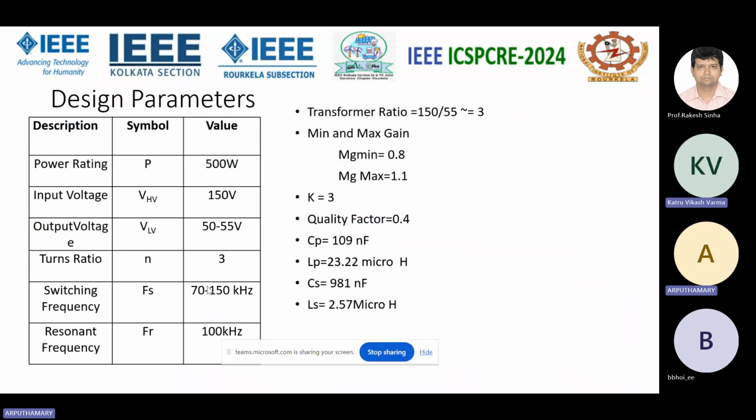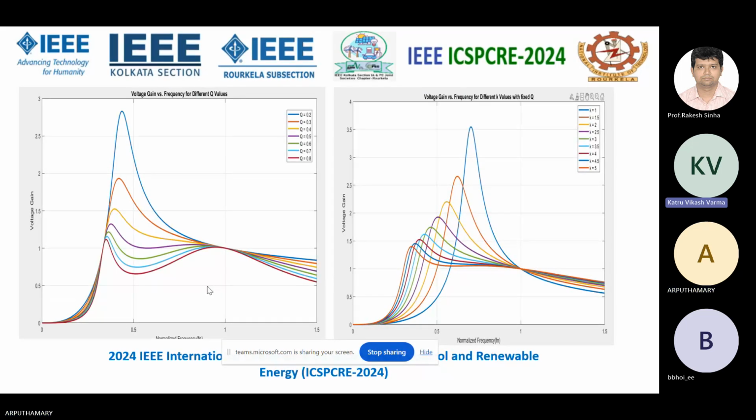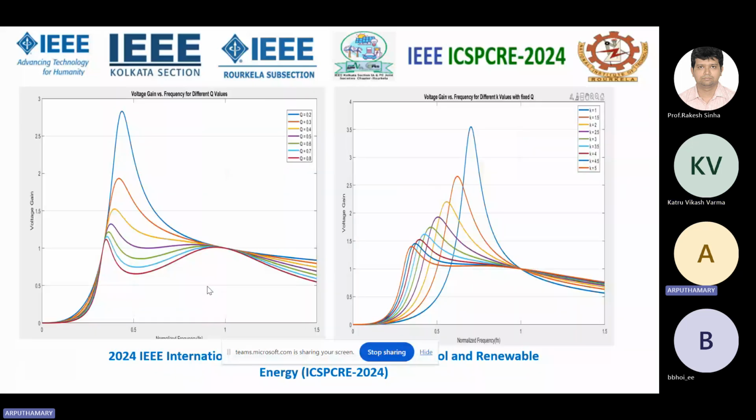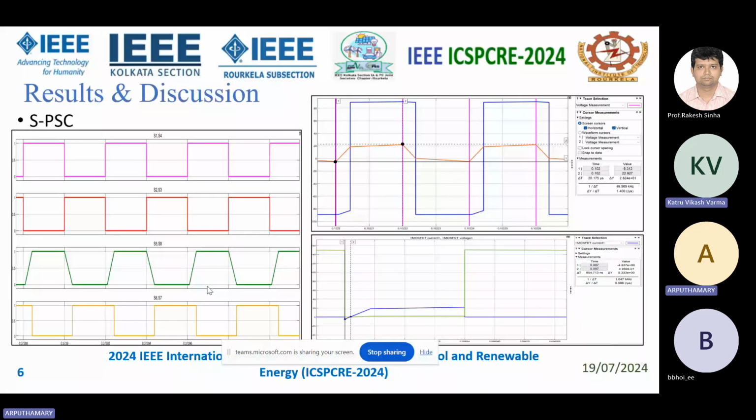Okay. And also in the SPS modulation, for the secondary bridge, your switching cycle is a little bit sloped. Why is it happening? Go for SPS. Sorry, I have given the phase shift of 30 degree. If you give 30 degree, the slope will come like this. I have zoomed out too much. If you zoom in to a proper switching frequency, it will give a square pulse.